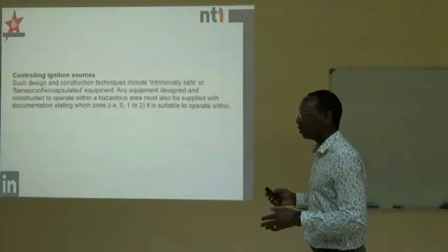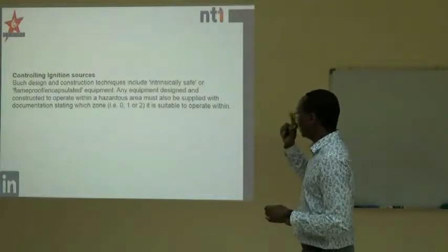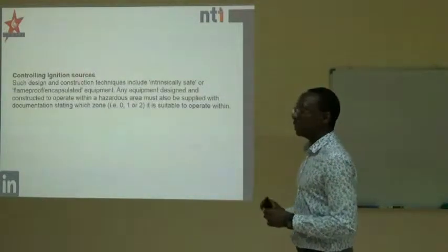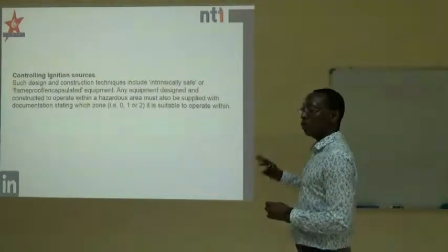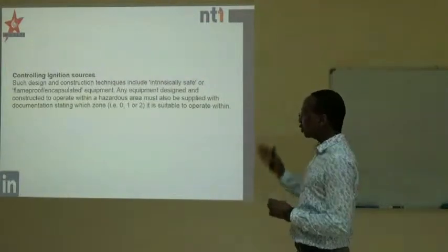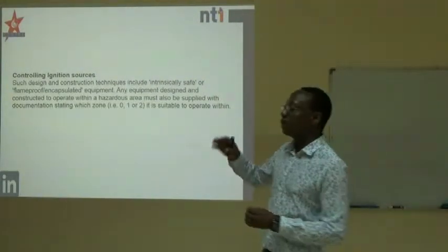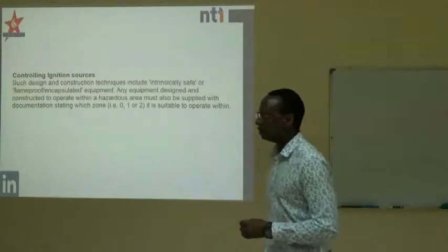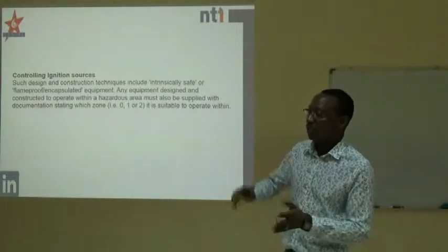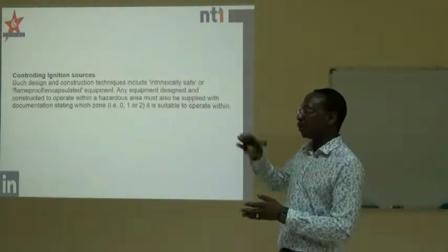Let me just go through it again. Zone 2 equipment for zone 2 or free zone. Zone 1 equipment can be used in zone 1 and zone 2. Zone 0 can be used in zone 1 or zone 2 or zone 0.